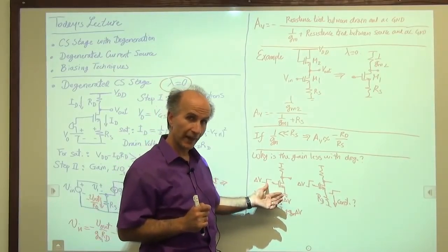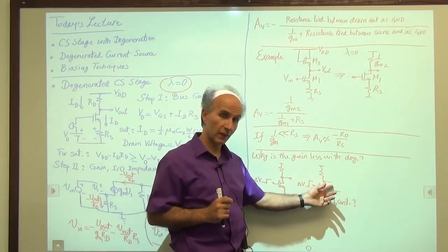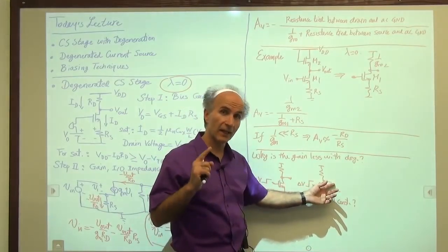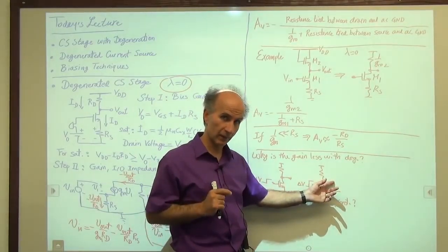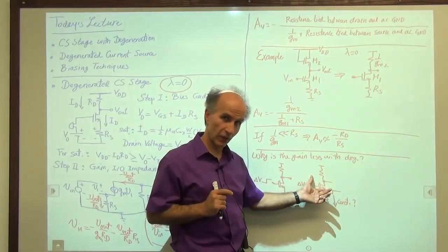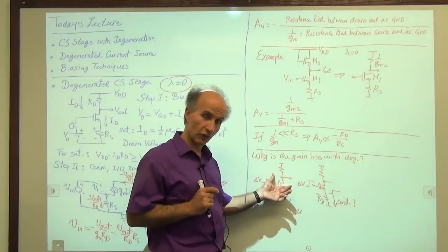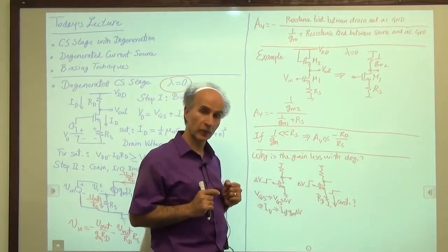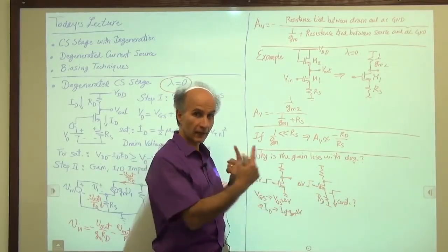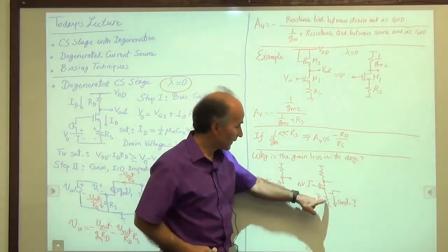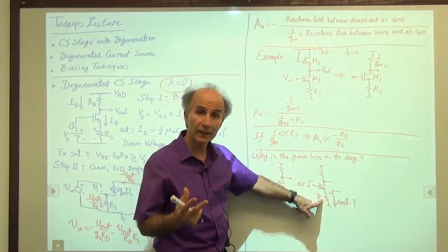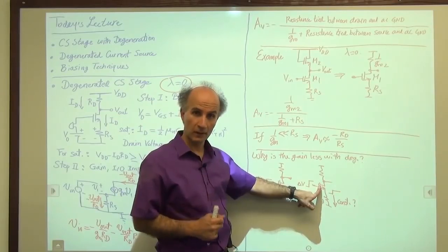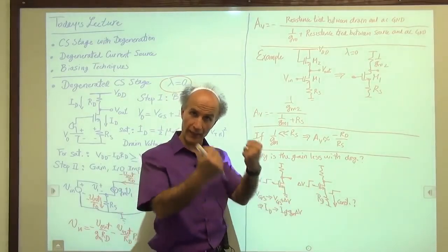That means that the change in the drain current here is less than GM times delta V because VGS changes by less than delta V. Whereas here, the change in the drain current is GM times delta V. That tells us right away that this resistor has weakened this transistor. This transistor here used to be strong. It had some GM.